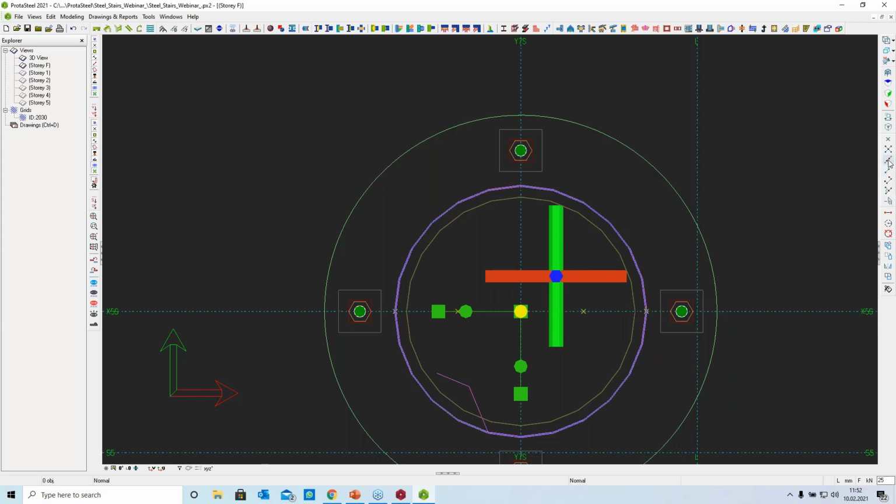Of course, for example, if you right click and type in, for example, 3, the software will specify 3 points between those 2 points. Okay. So now I will find the parallel points of these defined points. So let's select the points, parallel points, but first I will right click because I would like to type in 1300 millimeter here.